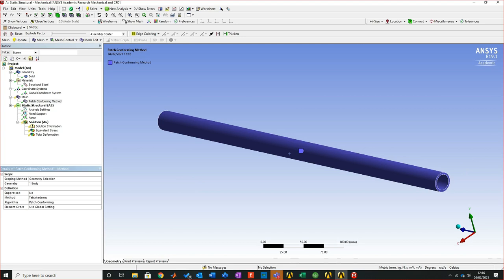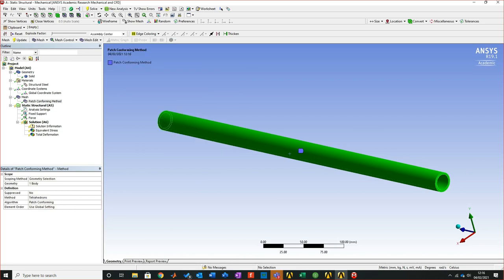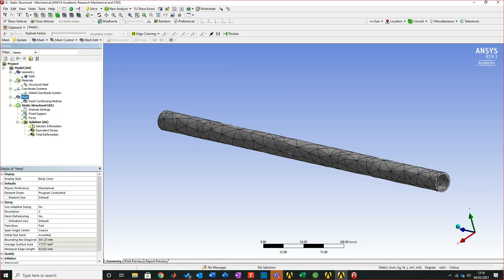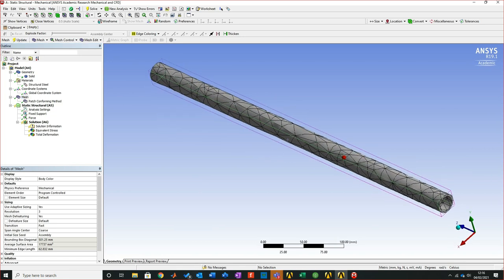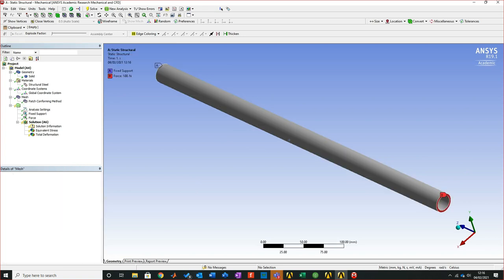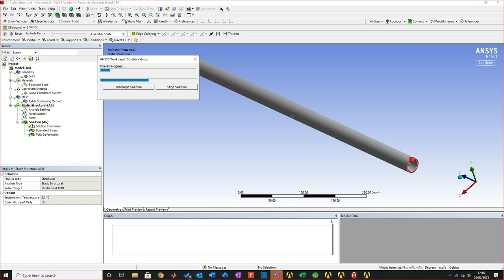So tetrahedral mesh. So yeah, this is actually going to make the tetrahedrons now. Now when you come back, you kind of look and go, what's it done? Click onto mesh. That is what it's done. Now, please don't follow me on this. I'm dying to show you what happens when you do a bad mesh. Now this is awful, but this will give me some great results to actually show you when you get people who say, okay, I'm just going to hit default.